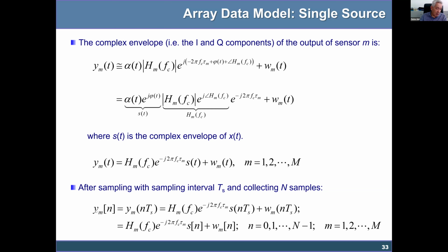So y[m,n] is the space-time signal, because n is the discrete time, and m is the space index, because it refers to the m-th sensor that is located in a different position. So the variable m takes into account the spatial sampling, and the variable n takes into account the temporal sampling. So the space-time signal can be expressed in this way.